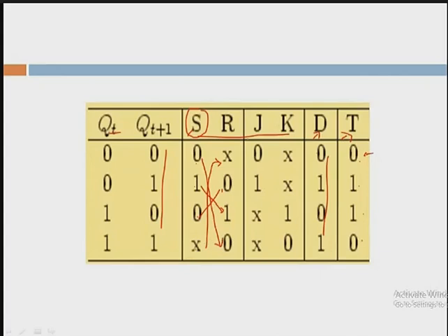Similarly, for the JK flip-flop, just recall the values of your J line and reverse this line while writing the K variable output. So here cross, this is a second cross, then this will be a 1 and this will be a 0. In this way, you can recall the excitation tables of your flip-flops.